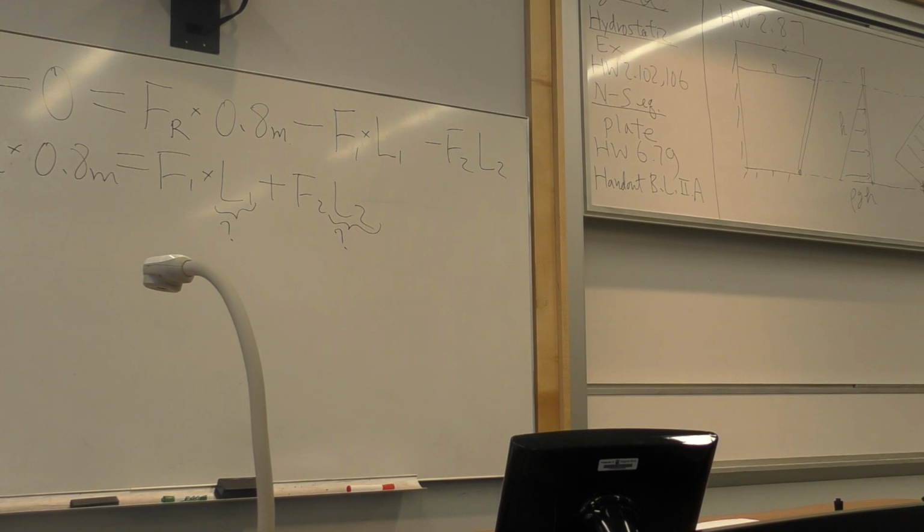I think what he was saying is that you can take that combined force and use the trapezoid centroid, then treat that as one force instead of splitting it into two forces. That is a lot harder. If that's the question, my answer is yes. But trying to find the centroid of a trapezoid is not easy. It's a lot easier if you take the trapezoid and break it up into a rectangle and then a right angle triangle. That's what we're trying to do.